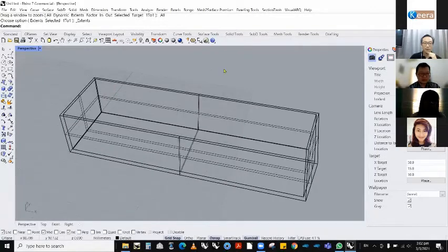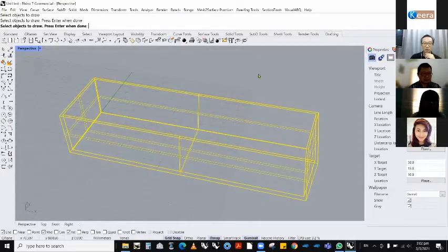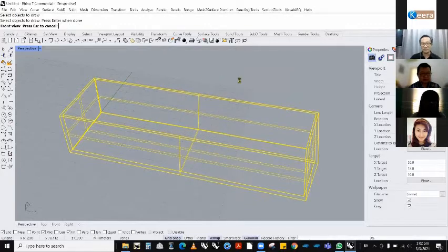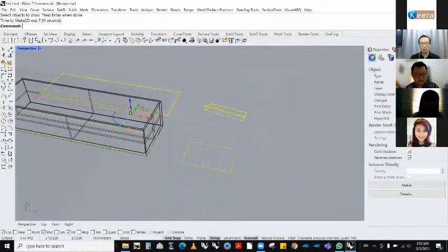First of all, if I want to go into drafting, I'll go into drafting, Make2D drawing. I probably want to make some 2D drawing, so either this, Make2D drawing, select my model, depending on how many angles you want. Once that's done, I say okay, hidden, this seems good. Just make a quick one, default, try it out if you want to. So the default is done, and it's generating the different perspectives. I will move these out.